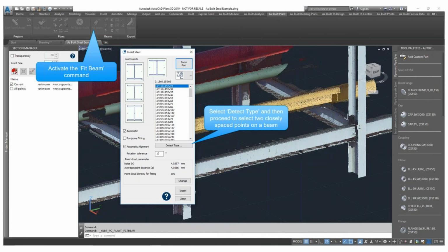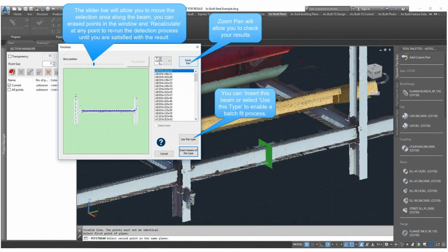for example, while you're placing these elements, we also have tools like fitting these beam commands, specifying the endpoints and snapshots, and defining where that element will lie when you model it. What would be the type of profile of that steel element, whether it should be the center of that I section, the top, or the bottom, and how the rotation of that I section will be. So you detect all that information and push it into this particular toolbox.